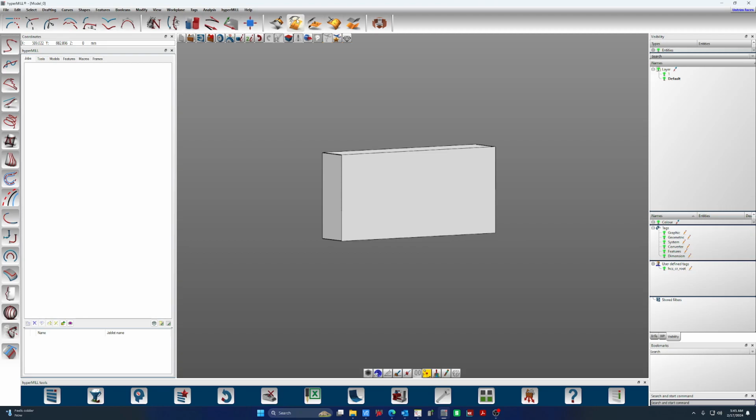and it will sort of revert it to its natural geometric shape, or at least turn it into an unbound or untrimmed surface that we can then extend and modify as we see fit, which works really well with the extend shorten face tool, which typically only works on untrimmed faces. To get extension surfaces on a face that is bound or trimmed, or basically the non-native face, there are some extension tools that we'll use instead.